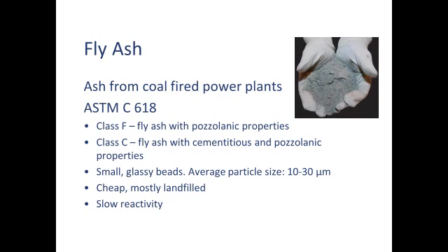It's, again, the most popular and most commonly used pozzolan in the construction world. And that's because fly ash, there's a lot of it, comes from burning coal. And coal is burned for power in a lot of places in the world. And there's a lot of fly ash generated. And unfortunately, most of the fly ash that's generated is still landfilled. The fly ash industry is trying to use as much of it as possible in concrete, and it's a very economical way of making your concrete less expensive.